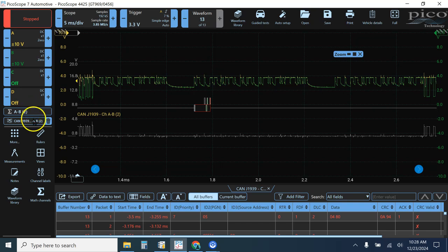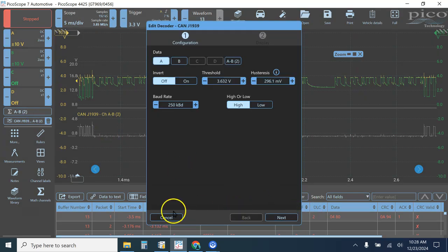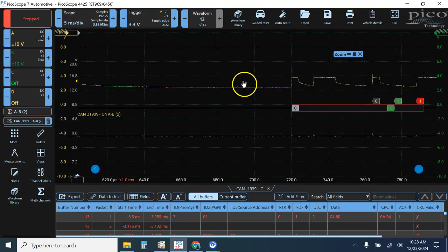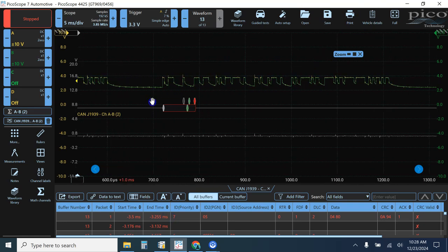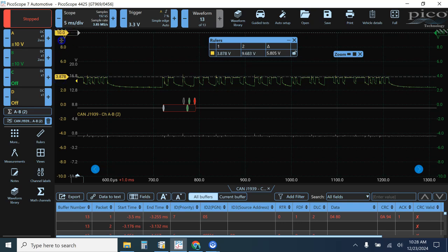So one of the things I can try is to look at this waveform again in a little more detail and figure out if we can decode this. Let's look at its amplitude. The peak amplitude is somewhere around 3.8 volts. The lower threshold looks like somewhere around 2.95, so about 3, so about 800 millivolts. If I could just look in that range, that would be great.